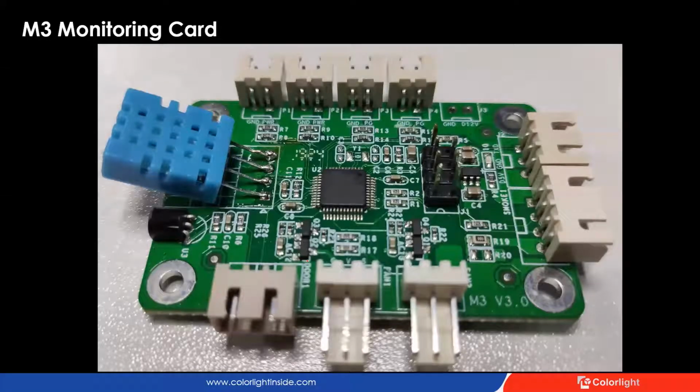Here I share a photo of the monitoring card, the M3. It can be used to monitor the temperature. Here, the black one, this is a temperature sensor on board. And the humidity, here, the blue one, this is a humidity sensor on board. And the power supply by 2 units here, voltage monitoring by 2 units here. We also leave the interfaces for smoke here, and electric fan here, and the speed of fan here. And the status of the door on the cabinet, whether it is open or closed, we could use this one to check.